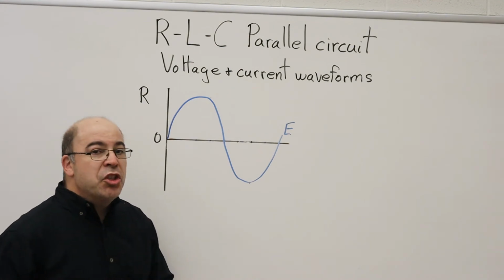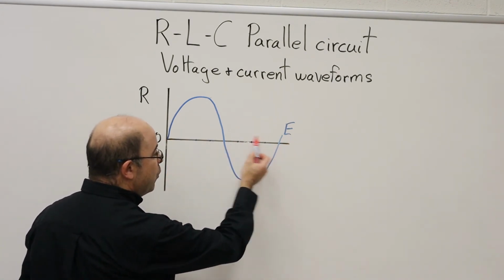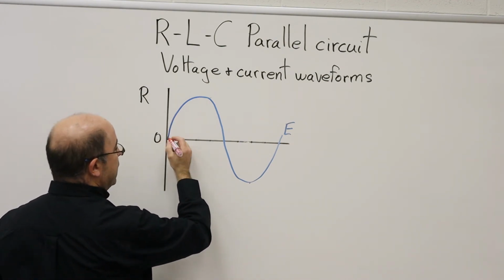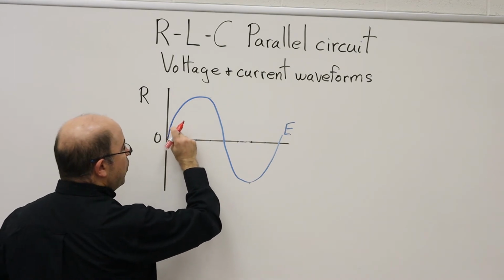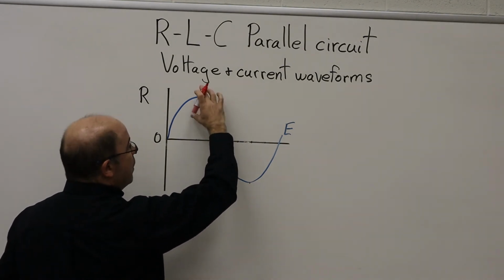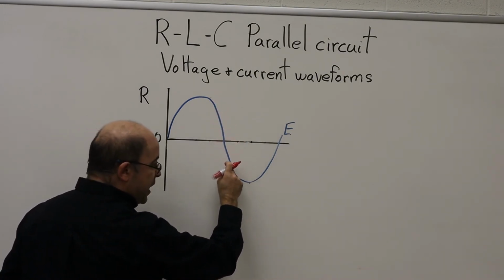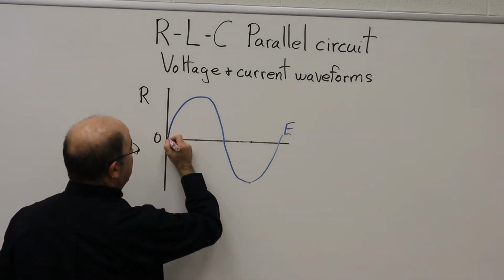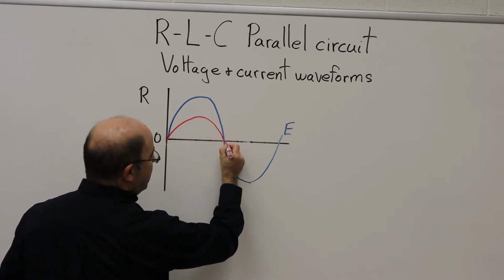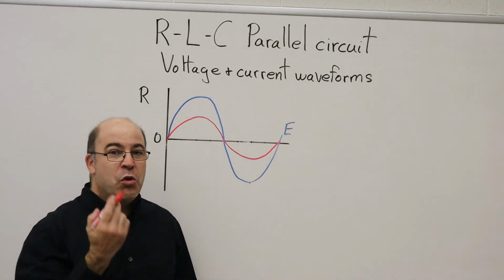Now, if voltage and current are in phase with one another, what does that mean? Well, it means at the point where they intersect here at this datum, or this zero line, which represents an oscilloscope, I should see that the voltage and current are starting at the same point. They would rise in unison, and then at this point where the sine wave is starting to decline, the magnetic field is going to start to collapse, and it is going to go back to zero and then proceed in the negative alternation. And this is what it's going to look like. We're going to rise, peak in unison, collapse in unison, cross over in unison, and continue the same trend, at least to the best of my meager drawing abilities.